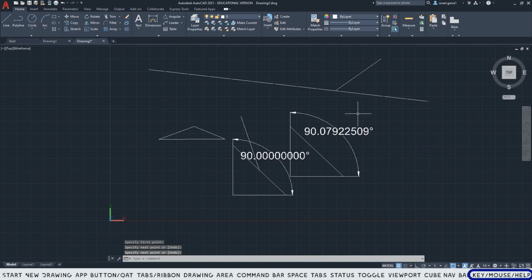And I'll do it again at the other node. So I'm gonna just hit L for line, enter, and slide along until I find it. And there it is, and I'll draw it again. All right, so now I've divided this line into 3 equal parts.